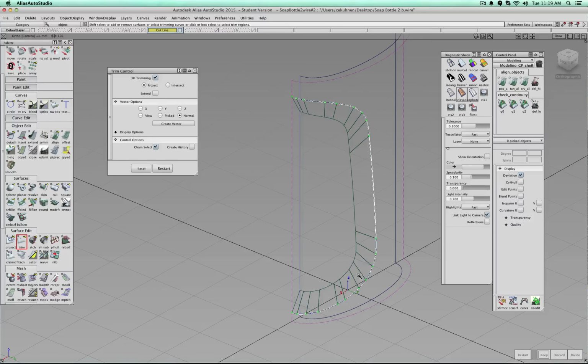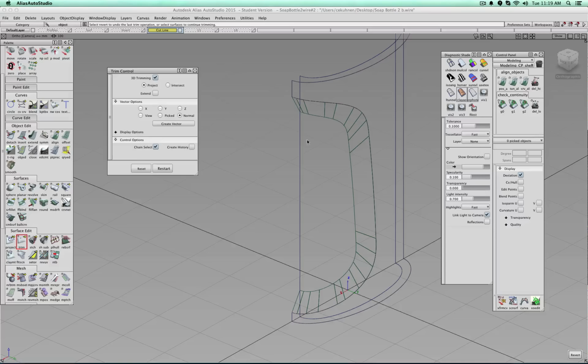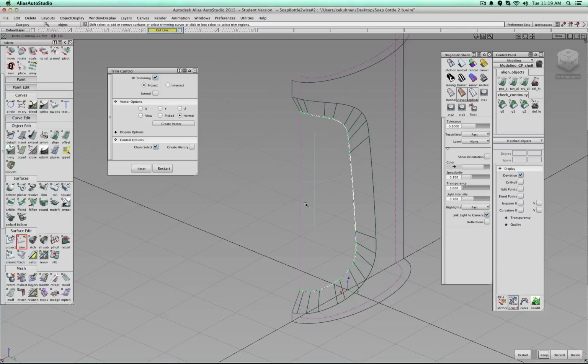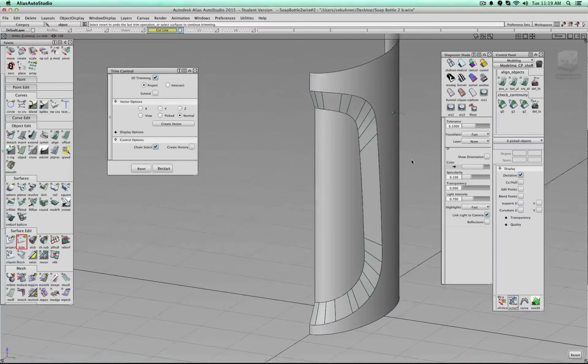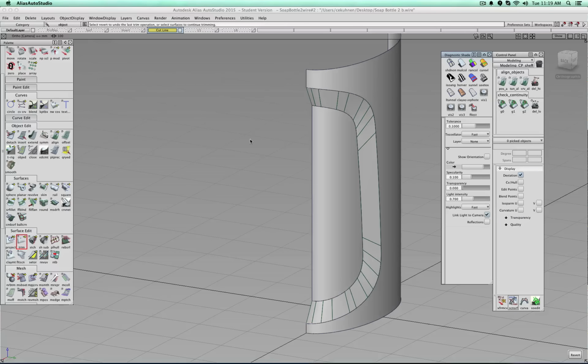If it does not, the surfaces do not rest on each other. Spacebar, click the part I would like to keep. Let's select the other surface, spacebar, click this area, spacebar. And there we cut everything. Great, so now we can remove that tool. You see it's not very difficult.